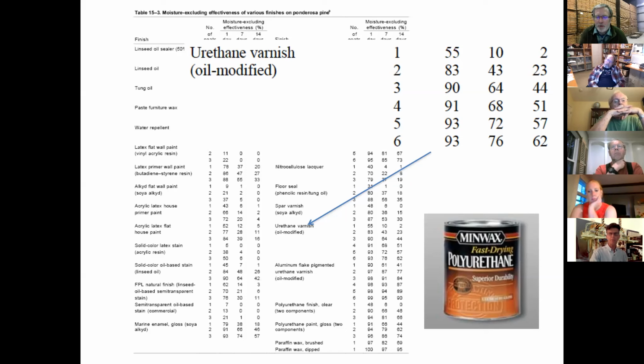The heat will come up. The relative humidity will change within 2 weeks' time. So it'll never reach potentially the worst conditions possible. In other words, you're slowing down the effects and reducing moisture uptake and loss, therefore reducing moisture movement. Now, not many people like 6 coats of polyurethane on their furniture, but it's significantly more effective than 1, right? The more coats you add, the more effective it is. And that's pretty true with all finishes.